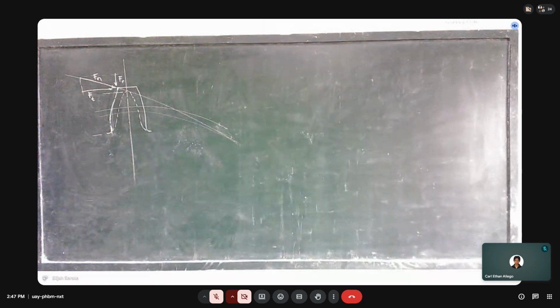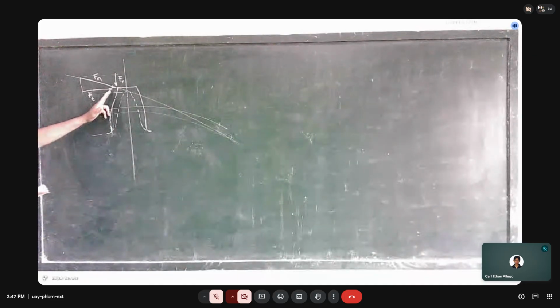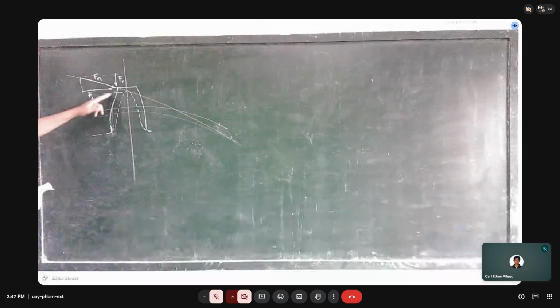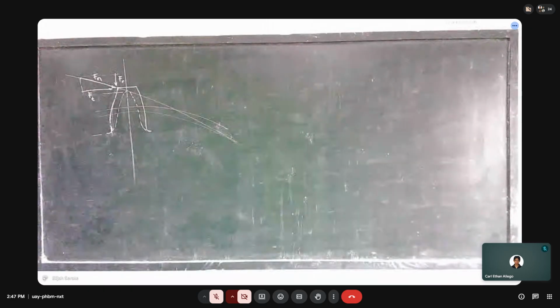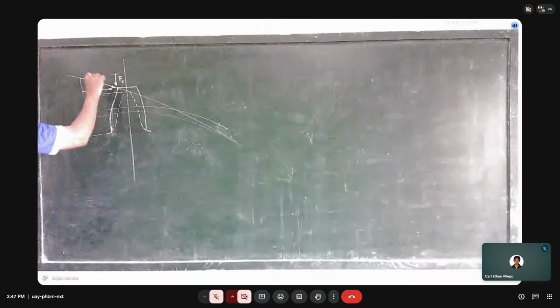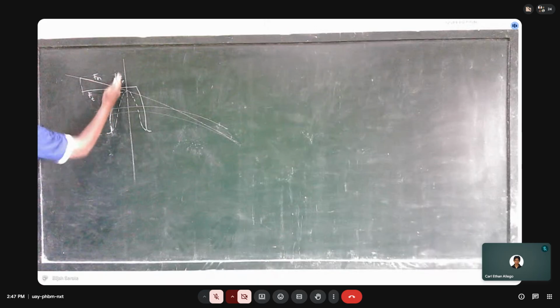Okay. So these are the forces acting on the surface of one of the teeth. This is the force coming from the driving pin. This is the reaction. Now it's made up of two components, no? Actually, the resultant is the normal force, which is perpendicular to the surface.